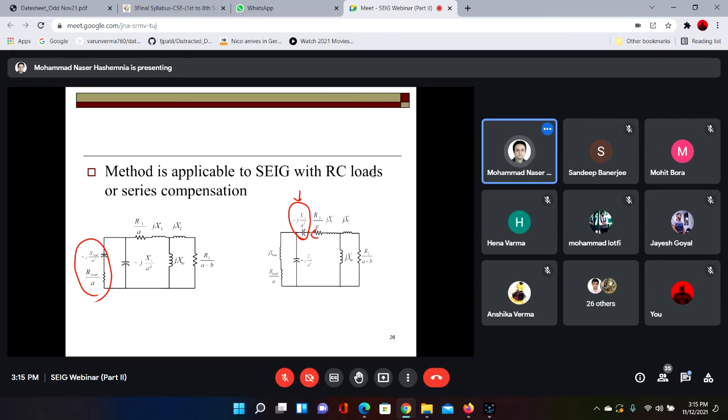In my method, it makes no difference. You come here, or in this circuit, you come here, and then you equate the value of the conductance across the magnetizing or the air gap branch to 0, and then you will find the A that minimizes the value of the conductance. After you find A, then you can find Xm.